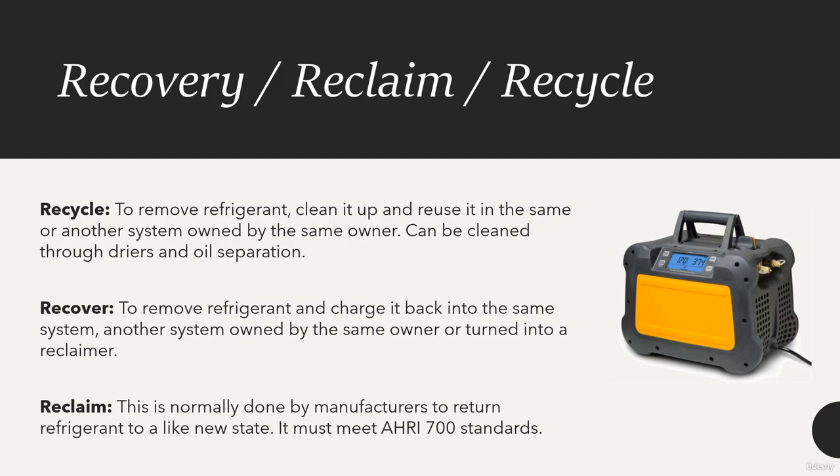The subjects of recovery, reclamation, and recycling are very important to understand the differences. To recycle refrigerant is to remove the refrigerant, clean it up, and reuse it in the same or another system owned by the same owner. It can be cleaned through dryers and through oil separation.